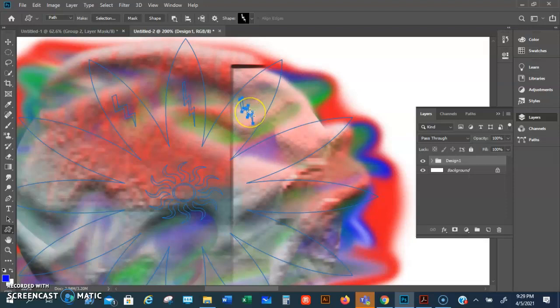All right, now do you see how this thing is not turned how I want, guys? What you can do is you can come over here, grab this tool here. While this is selected, I can hit Control T, which is free transform, and then I can rotate that one. And then I can go back to my shapes and do it all over again. I can see that this is not turning how I want it to be. It's selected. Control T. And then I'm going to raise that up. Drop it in there. Something like that.